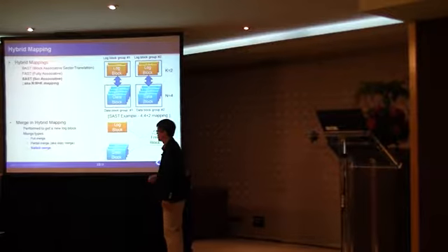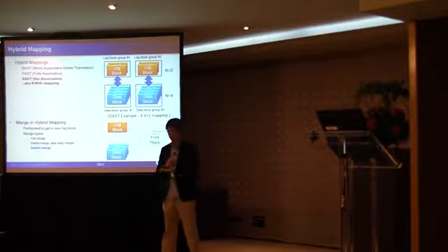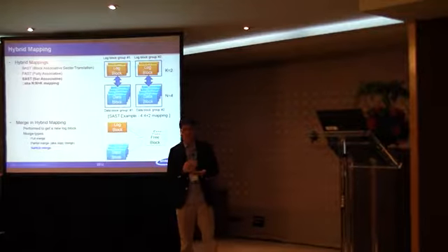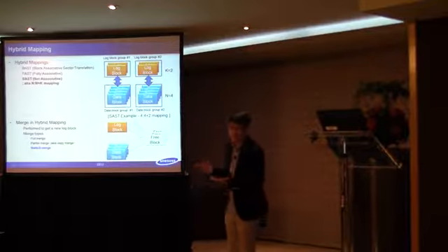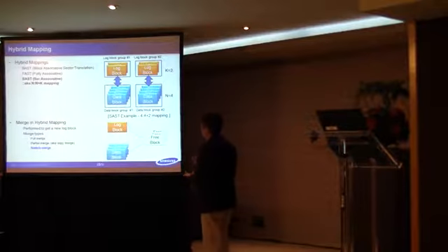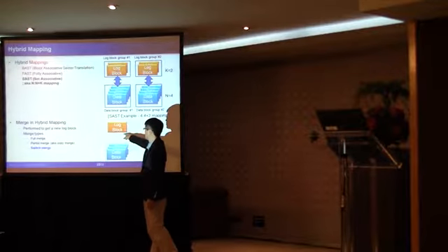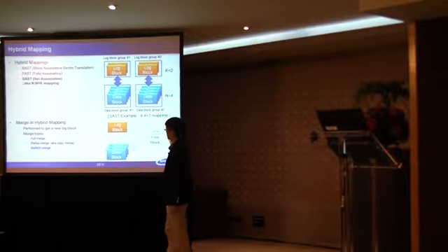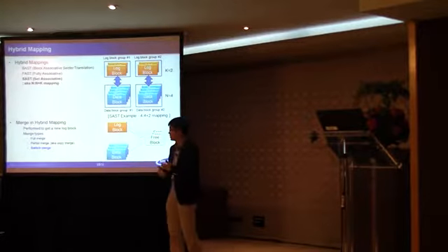This can be achieved by a sequential write pattern. So if we write from the first page of the block to the end of the block, then it is very simple to merge that block, because we just use the log block as a new data block. So we don't have to copy the valid pages, but we change the mapping entry.